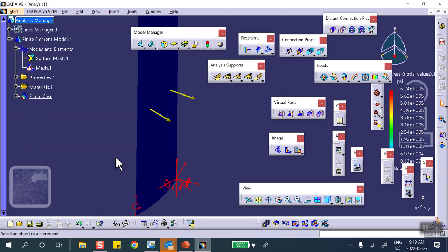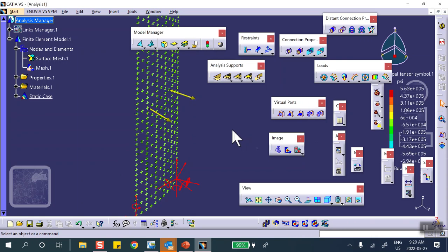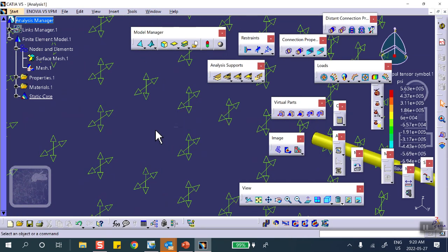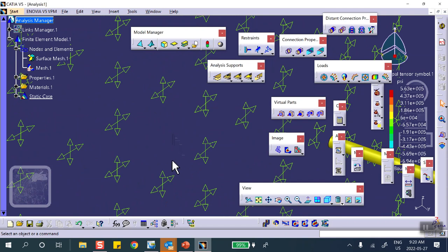But if you plot the principal stresses, it will actually give you PR over T and PR over 2T. Because for principal stresses, one of them is the hoop, the other one is the axial, and the third one is zero. So if you go and plot the principal stresses, which was totally useless for beams, here you can actually get things that you did with Dr. Green and whoever taught you in the first course.